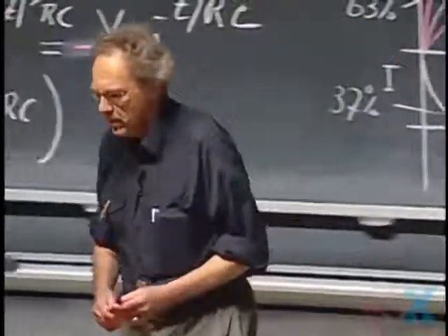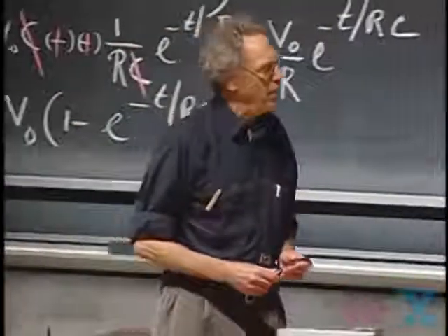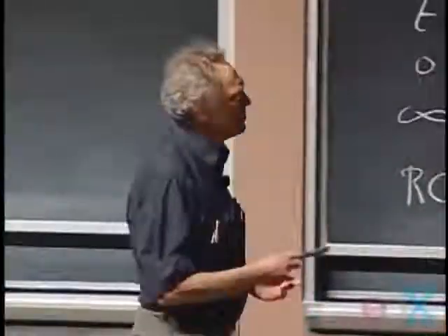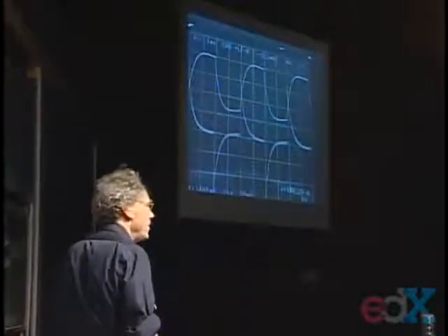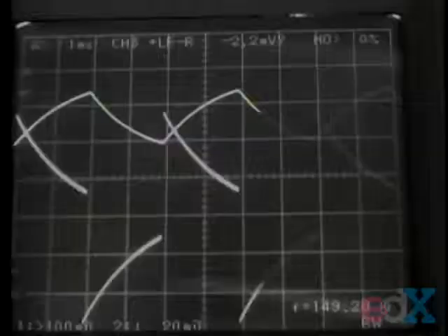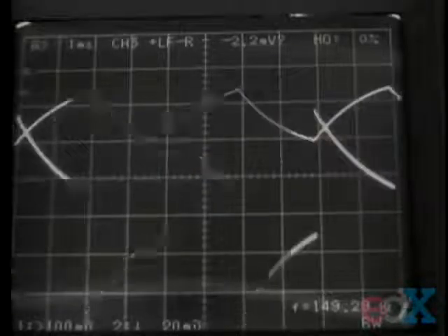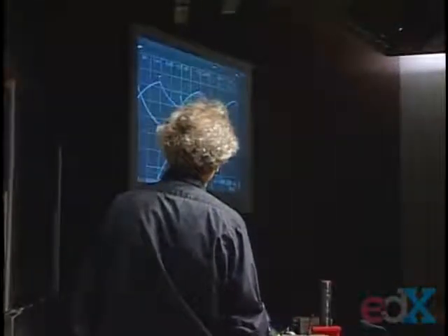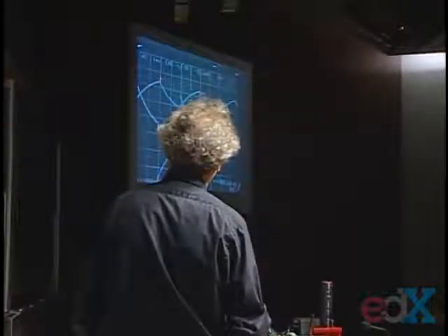What I can do now is to increase my capacitance by, for instance, a factor of 5. So that would change my RC time to 3 milliseconds. So now there is no way that the capacitor can become fully charged in the 4 milliseconds that it has. And you will see that indeed, if I make this 0.5 microfarad, then the capacitor has not enough time to get fully charged. And so here you begin to discharge.